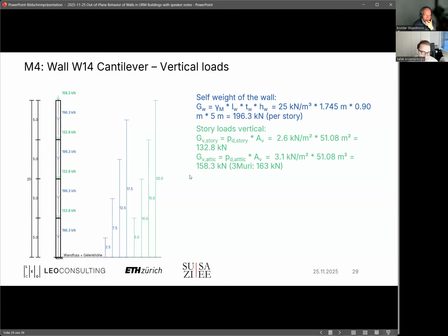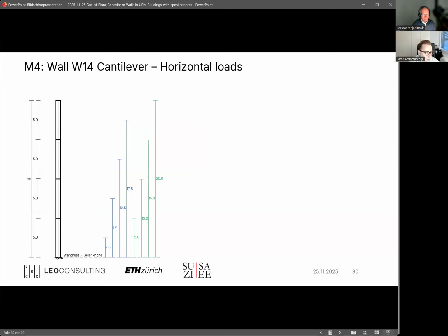And here are the forces. I also did this check with the Tremuri software just to see, and there's a quite good match. And then we can continue and focus on the horizontal loads. This is the essence of the rigid body motion, rigid body kinematics. So what we do here is we already assess the self-weights. We know how big they are. So we solve, they are roughly 200 kilonewton.